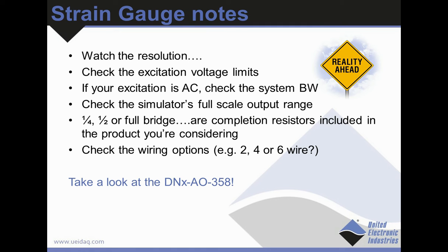So a few notes on strain gauges, and in particular strain gauge simulators. Watch the resolution. There's a fair number of switched resistor out there. Make sure you're getting the resolution you need. Other things to watch out for is the excitation voltage limits. You need to make sure it's compatible with your system. There are AC strain gauges, and if so, make sure that your system can provide the bandwidth required. Again, check the simulator's full scale or the SIL's full scale output range, and make sure your strain gauge simulator